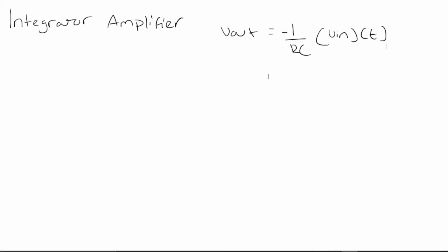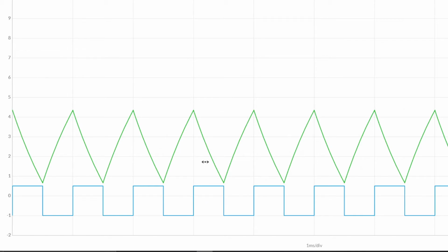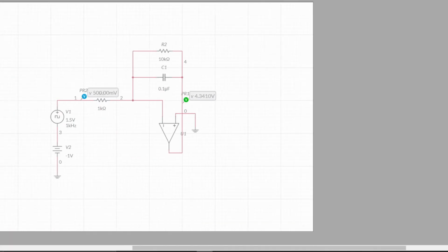I'm going to show this in Multisim as it's much easier to explain. You get a visualization. Here I'm running the integrator circuit. We have our resistor, our capacitor. This is a standard integrator circuit. And we also have the resistor here in parallel to the capacitor, as this provides a DC feedback for stable biasing. You don't really know much what's going through just for these numbers, but very interesting, we have a square wave going in. We take a look at the graph and we get a triangular, like a sawtooth wave, I believe it's called. I'll just call it a triangle wave. But yeah, this is the integration of our square wave. We get a completely different waveform. It's very, very cool stuff.